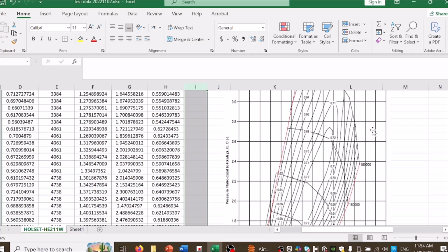And at the end, what is the relationship between airflow and engine power? More airflow generally means more fuel can be burned, which means more potential power. So more airflow equals more power potential, but only if the turbo is operating in a proper range. And why does temperature matter? Compressing air raises its temperature. If compressor efficiency is low, outlet temperature goes up, air density goes down, intercooler load increases, knock risk increases in engines, okay? Gasoline engines.